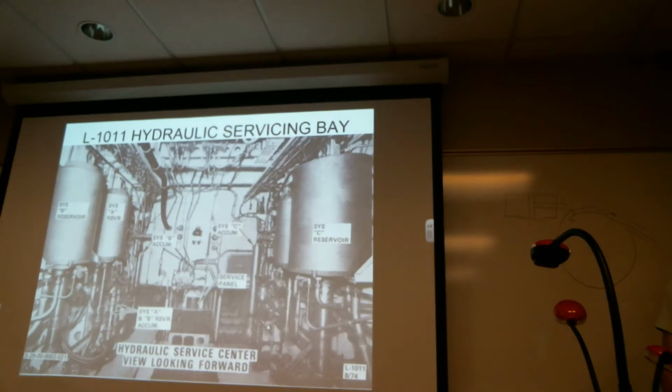Okay. Some complications in servicing reservoirs. If the aircraft is equipped with bootstrap reservoirs, servicing is somewhat of a problem because they don't have a cap on the reservoir itself that provides for servicing. Generally, with a lot of the bootstrap reservoirs, they're serviced by means of a ground service cart or a pressurization device to fill the reservoir or service it back up again.